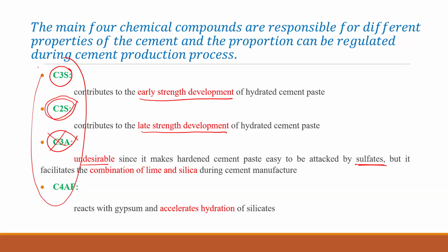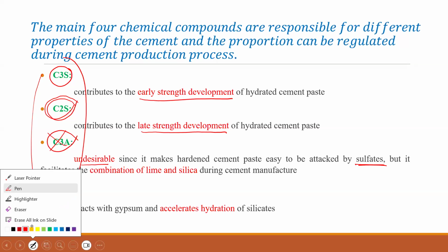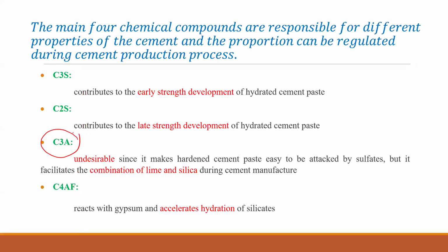And also there are other precautions. I will explain them later. There we can have admixtures, or else we can have air entrained concrete. Don't worry about those things for the time being. Just remember that when we have a higher amount of C3A, if you are using that cement in a sulfate affected area, that will be a problem, because it will make the concrete swollen.